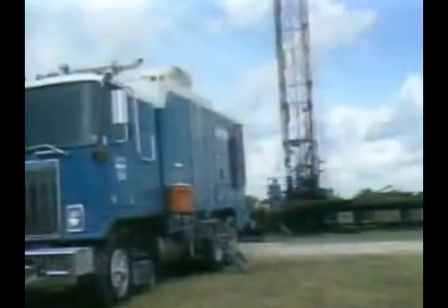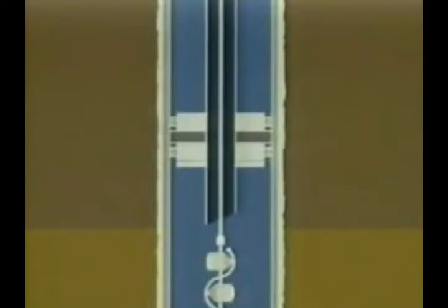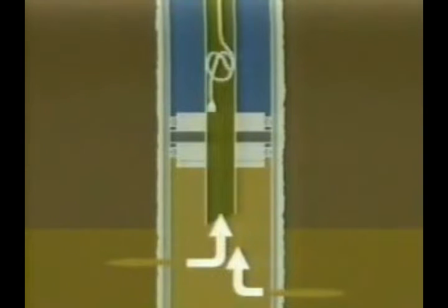After firing, the well is typically flowed for 15 to 30 minutes before the gun and/or cable is recovered. It is important to design the degree of underbalance to prevent blowing the cable up the hole due to frictional forces imposed by the flowing cushion fluid.